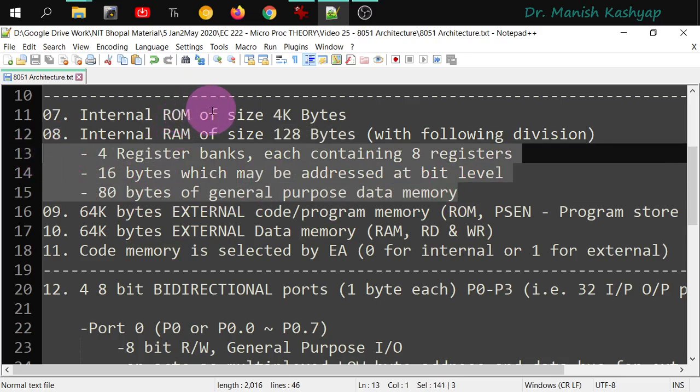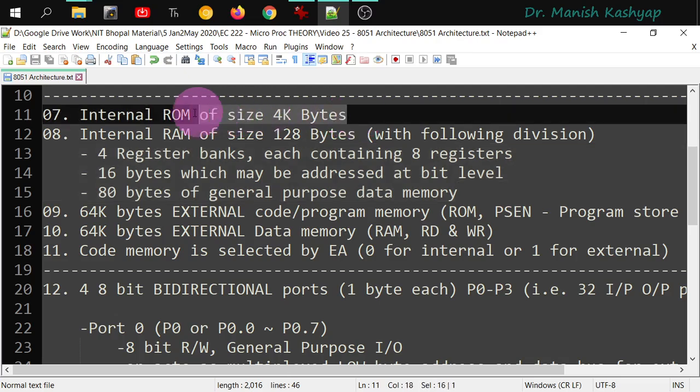In ROM, you will usually write your programs, and once a program is written to a microcontroller, for example, microcontrollers you can find in your washing machines, your air conditioners, etc. Once a program is written to them, that hardware is attached to a bigger hardware, and it will be used forever for that purpose. So in ROM, we will write programs permanently. It will hardly happen that inside a microcontroller we will need to change the program. So we would prefer to write our programs in ROM.